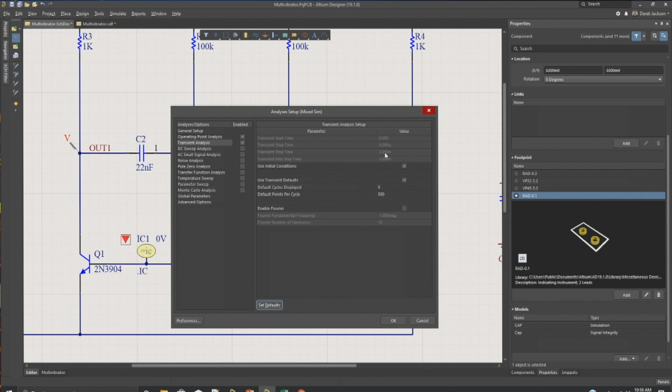A lot of times when you're looking at a sinusoidal source and your waveform is really choppy and all sawtooth, coming in and adding more points can help. And of course, if you uncheck that here, you can set those up manually as well.